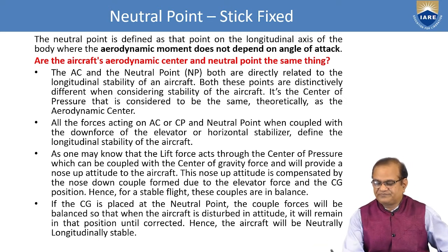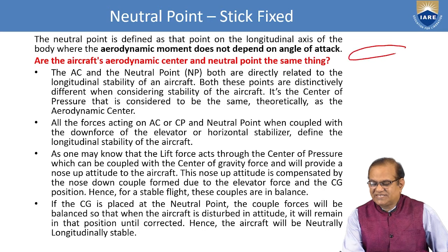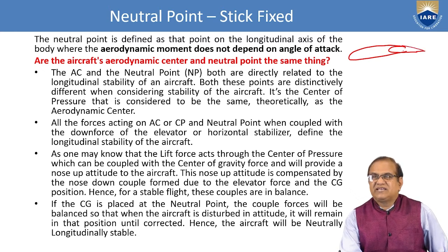If you see here, this is the elevator, this is the horizontal tail and this is the elevator. If we change the angle of attack, this elevator will also produce some lift, and this lift will try to move this thing up and down.